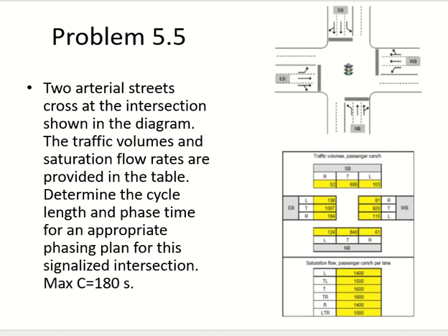To decide whether this left turning should be permitted or protected, take left turning multiplied by the opposite through movement, and then look at how many lanes you have for the opposite movement. 2. So for 2 lanes, this number should be less than 90,000. If it is 90,000 or more, then you have to make it protected.